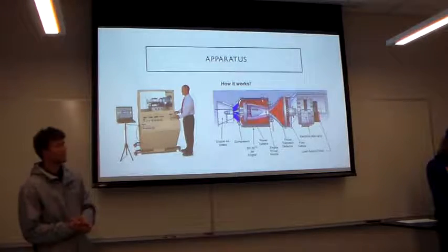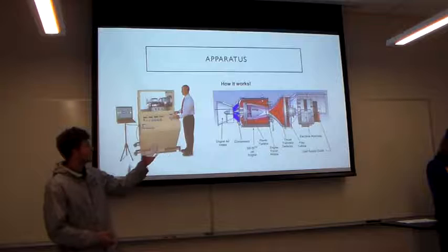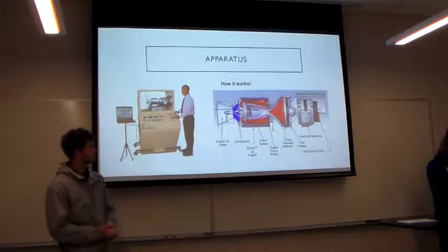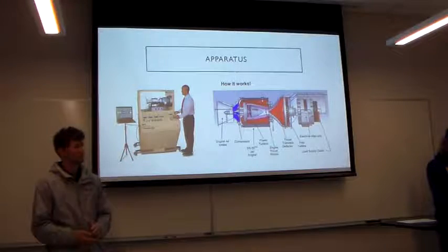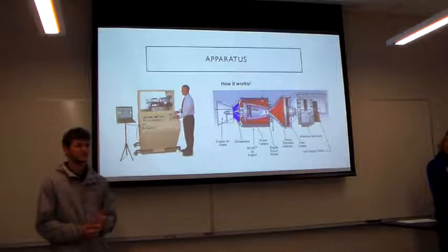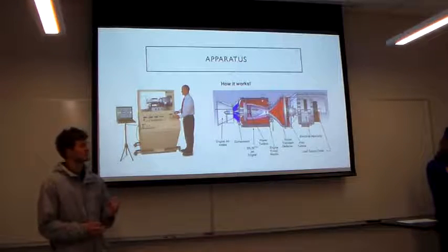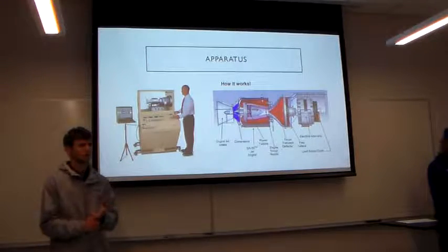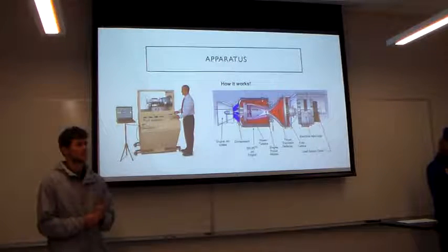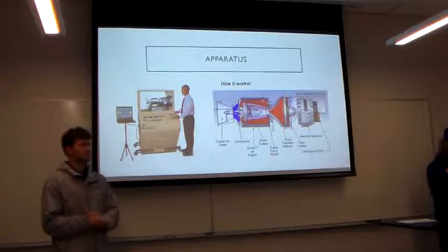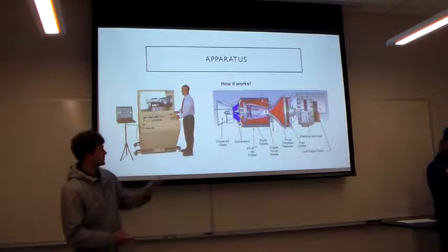It breaks everything down. So basically, we have ambient air come in to the intake. The pressure is brought up through a compressor. Then it enters a combustor where it's burned. And lastly, it's expanded through a turbine. These three components, the compressor, combustion chamber, and the turbine, make up the gas turbine, so to speak. And this really becomes a jet engine when you add that nozzle to it.